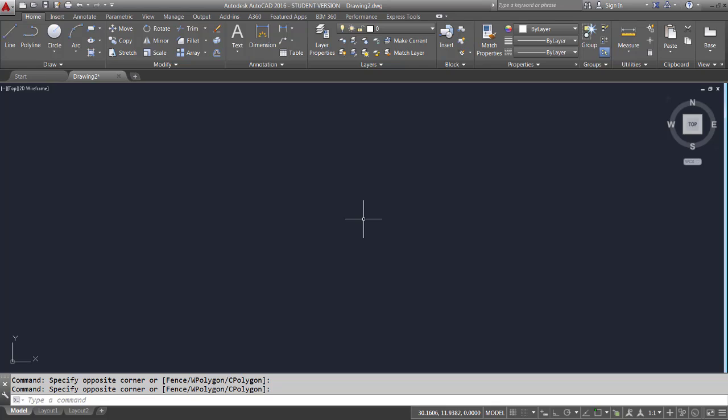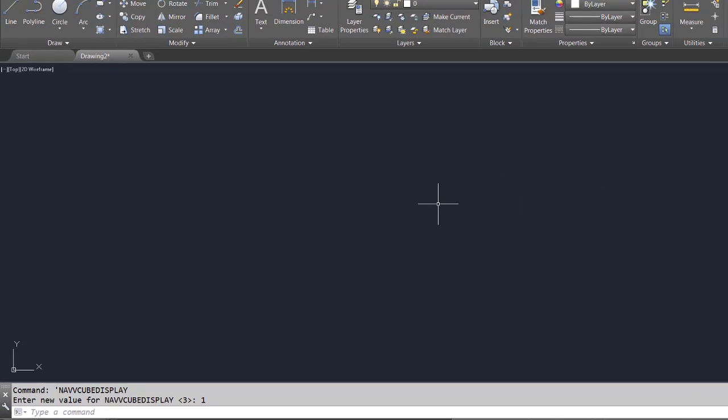Okay, so we're looking at our blank screen and ready to draw. I did just notice that up here in the corner we have our view cube popped back up, even though we had turned that off in an earlier video. So AutoCAD does that every once in a while. Sometimes things kind of pop on and off. You're not exactly sure why, but we can always go back and control that. So I'm going to go back up here to our little flat bar and turn off the view cube. So now I do have, in fact, a big open clean drawing area.